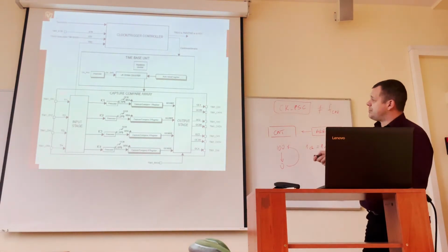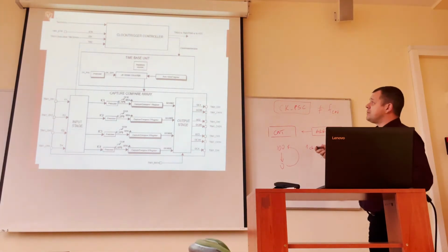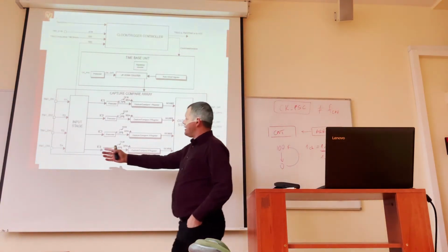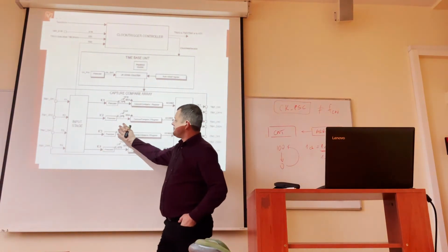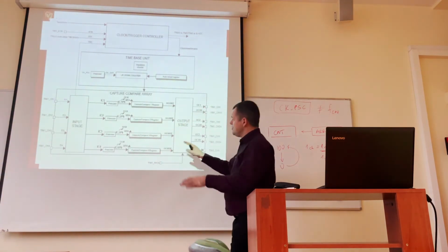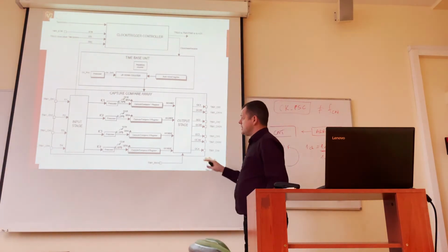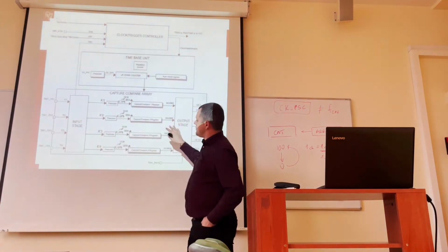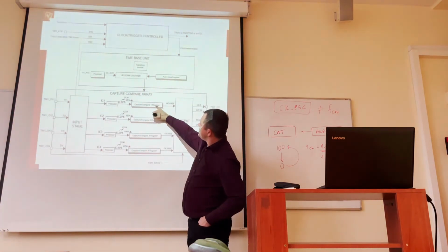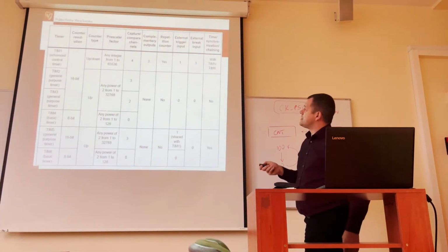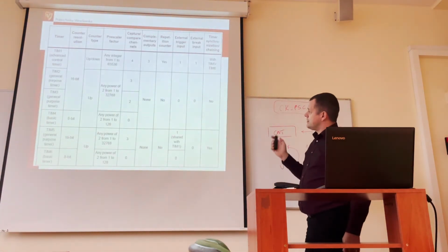Then we've got this capture compare array, which is additional functionality, because the counter is the basic one. Here we have, first of all, counting of the input, observing of the input signals. So we've actually got 3 functionalities with this capture and compare array. The first functionality is maybe not left and right, but the middle, because in the middle we've got these compare registers, if they are available, because as you can see in this table, for example, here and here they are not available.